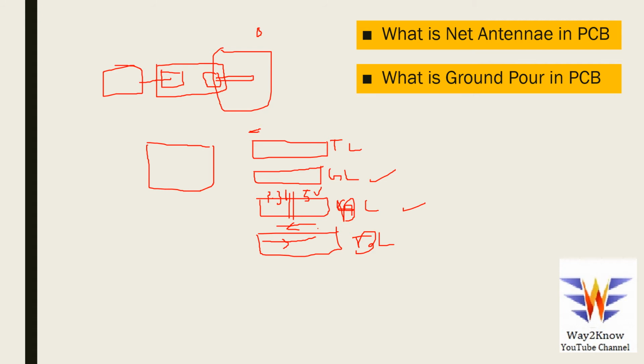So what we do is, as we discussed initially, we will have vias to a ground plane, and then this via extends till the top layer. So you will have a ground plane via to ground plane. So the connectivity is only till the ground plane, and if you see on the top, there will be two wires that will be coming this way.